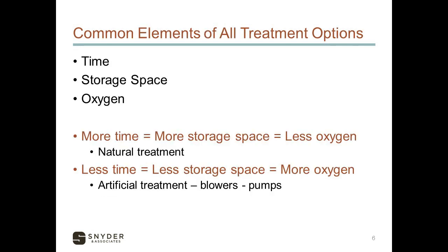As I get started, I just thought I'd remind you all that all wastewater treatment needs have some common elements, and one of those is time. How much time does your water have in your system before it moves on? How much space do you have? If you have more space, you can get more time, and that would require less added oxygen. In other words, nature can provide enough oxygen. That's how the controlled discharge lagoon works. If you have smaller storage space, that means smaller time available to store that wastewater, and that means more oxygen required through artificial treatments with blowers and pumps.